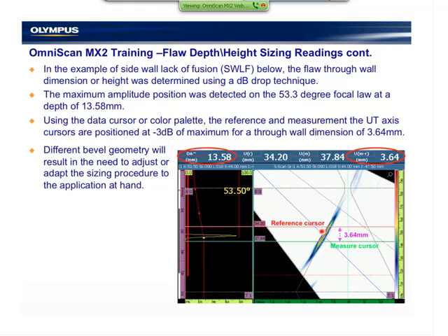So if the flaw appears at about 80%, like this one does, and we can tell from the color palette here relative to this, typically new inspectors, junior inspection companies, or per jobs where there hasn't been any or little upfront engineering for refining the sizing technique, people would generally oversize the flaws. So we want to be conservative. We can see here the 3 dB drop and the 6 dB drop position. Somewhere in between those, based on your weld bevel and your weld process, we will determine.